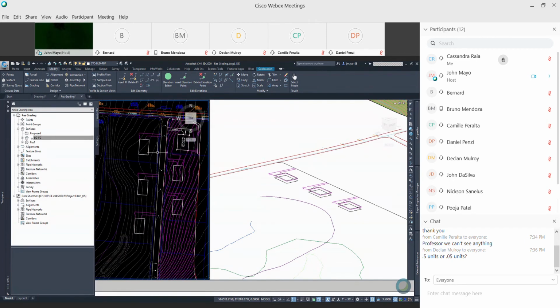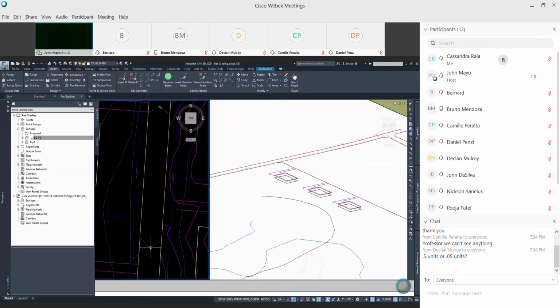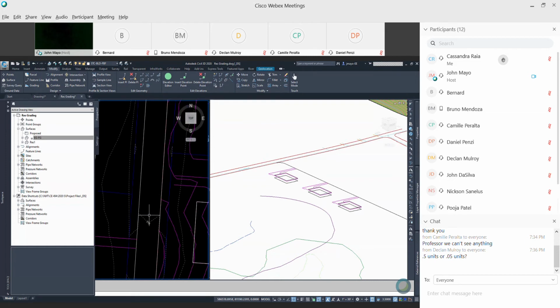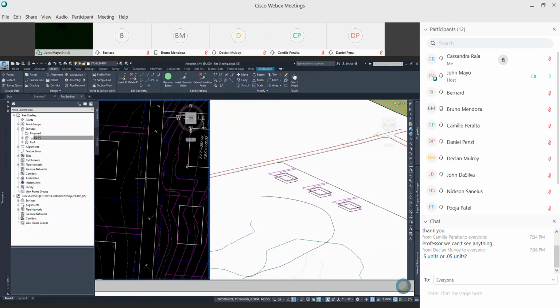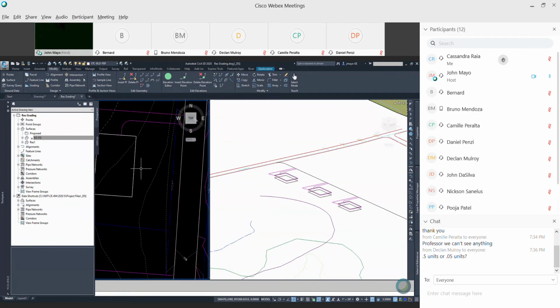All right. So I said we want our first floors 2 feet above the high point of the road. This is my high point. I'm going to assume it's 1/2 of the interval, so 377. 2 feet above is going to be 379. So move all of this. And I can even take these guys too. From here, let's go move at 0, 0, 379.